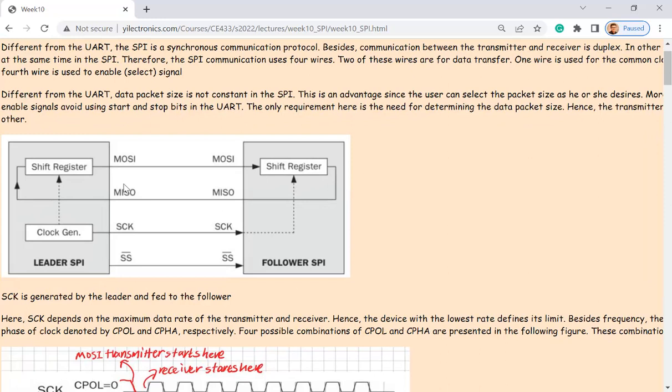We have used SPI in microcontrollers, so we do have SPI modules on our Arduino chip. So the advantage of using SPI over UART: UART has only 2 pins, RX and TX. It doesn't even have a clock because you specify the baud rate in the digital module already, either 9600 or something else, right? So they know each other, like what is the transmission rate for the two modules. But here you have a dedicated clock and you have more pins. So there are more modules.